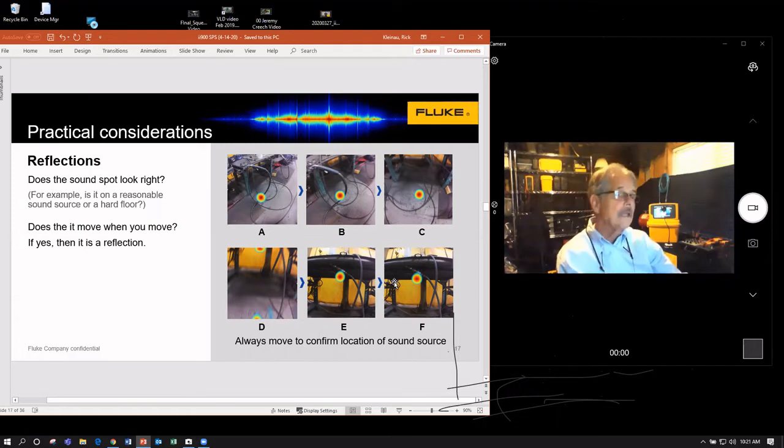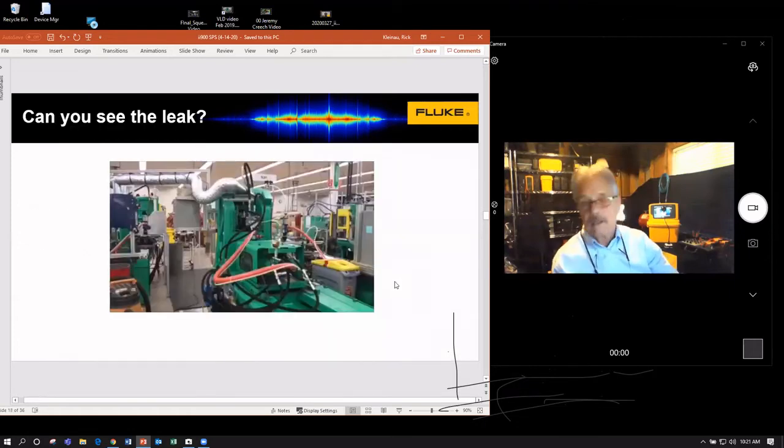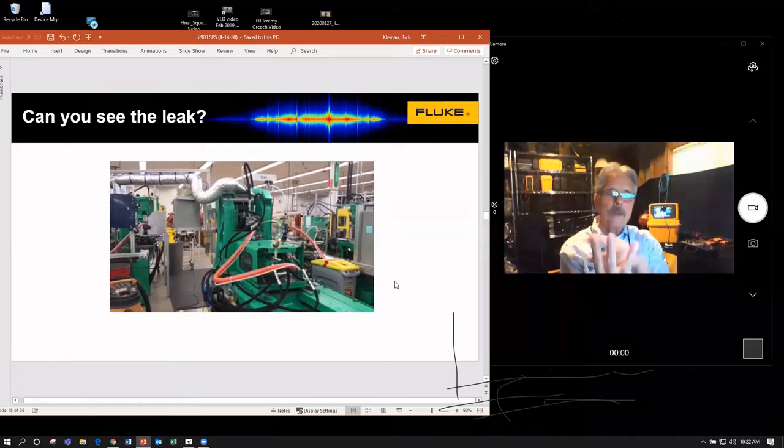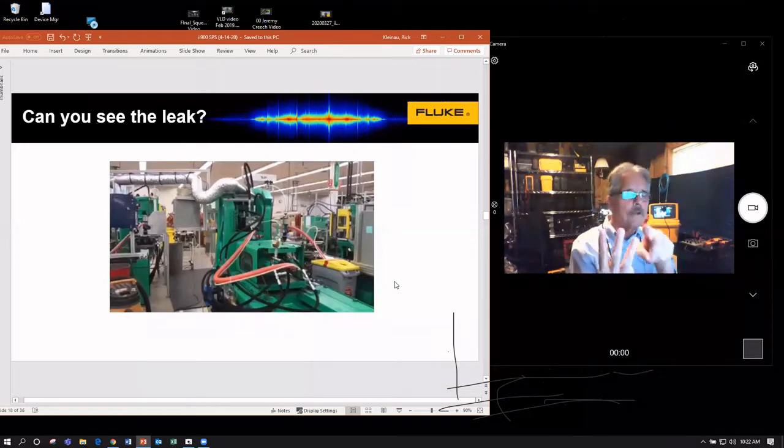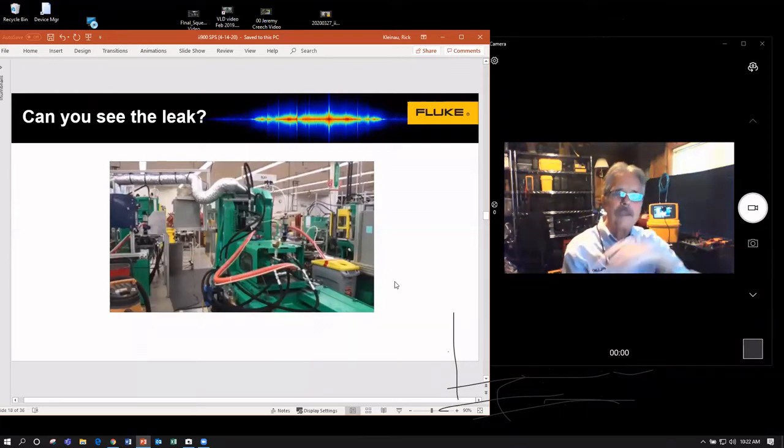Now, it's likely there are some folks here with thermal imaging experience. I know you guys at Statesville Process Instruments have been involved with thermal imagers. If you look at an electrical panel with a thermal imager and you see maybe a three-phase connection and one of them looks hot, you see a red spot on it, but you move a little bit and that red spot moves over to the next phase or someplace else.